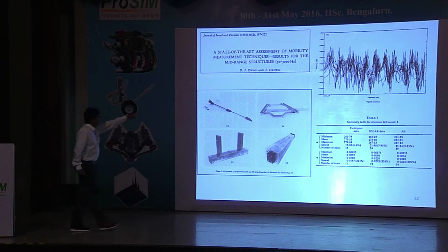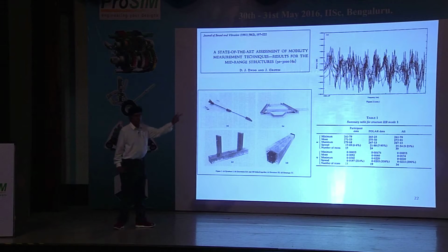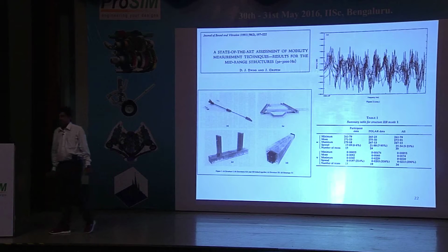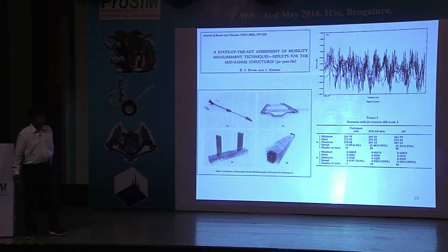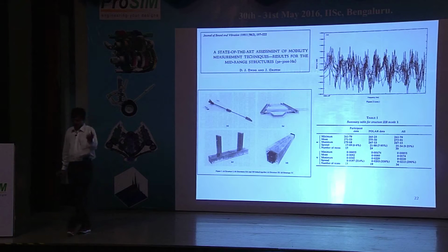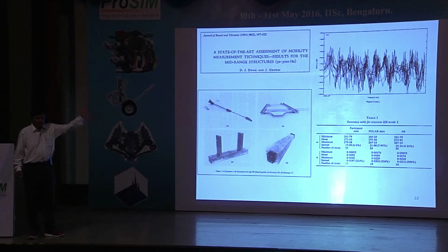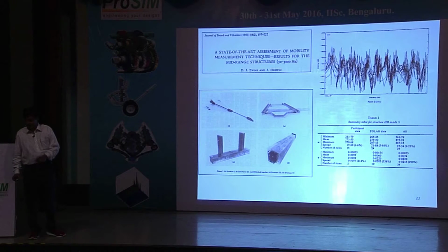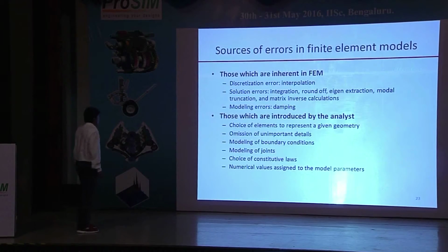So what you see there is the ensemble of frequency response functions reported by experts. It showed about 8% fluctuation in the first natural frequency, much more at higher modes, and about 225% variation in damping. This is done through experiments. Okay, so what is the moral?